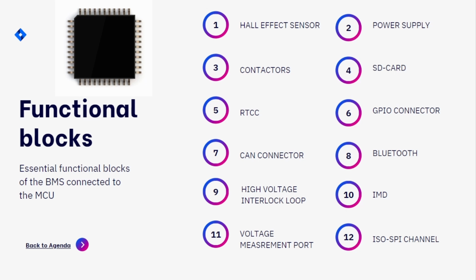Generally, the battery pack system has 3 different contactors. The first one is a charge, a discharge, and also the pre-charge. There will be only one contactor for charge and discharge in some applications, like an energy storage system. The BMS controls the switching of the contactor through a driver circuit also. So the BMS will give energizing signals to the driver circuit, which energizes the contactor for the operation.